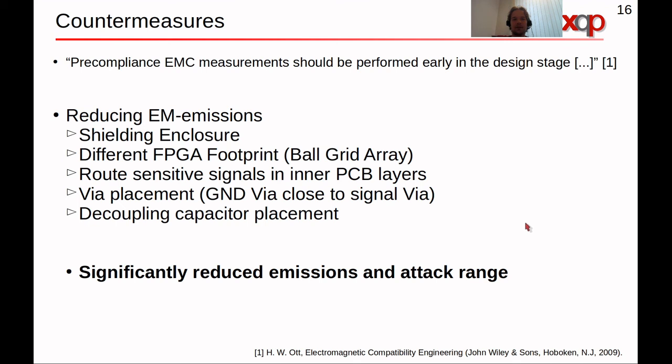And I want to mention some countermeasures. It is well known in the field of research that is concerned with such emissions, classical hardware security, that measurements and countermeasures against such leakage of information should be performed early in the design of such devices, because fixing such leakage after the fact is much more difficult, and just shielding often doesn't suffice.